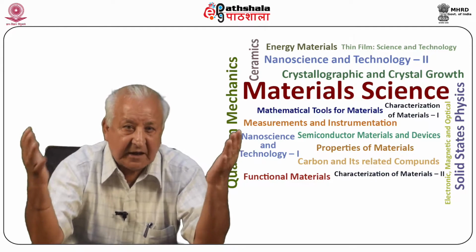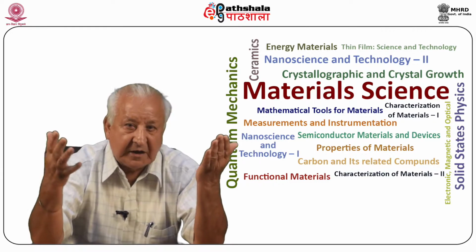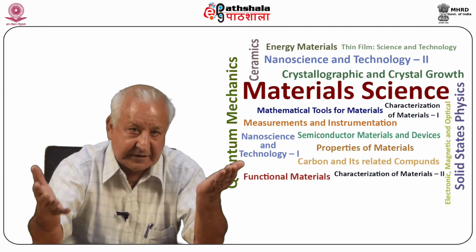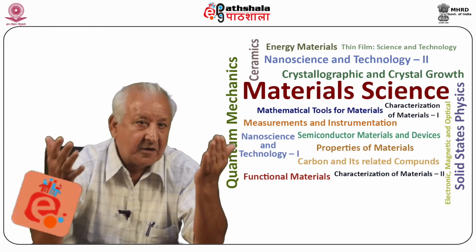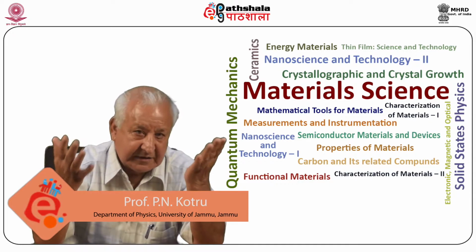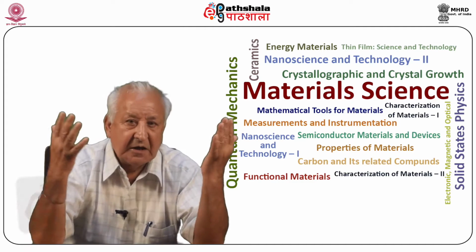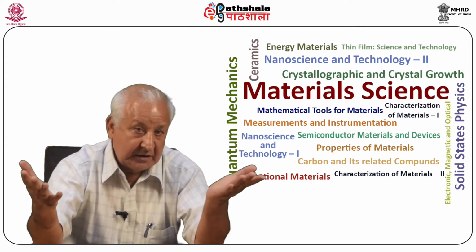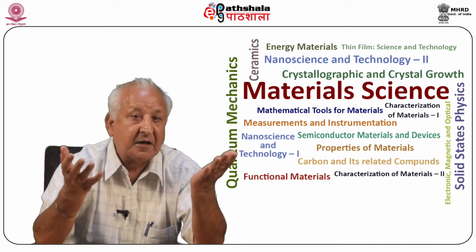Zone melting as a technique of crystal growth is explained. Floating zone technique of crystal growth is also described. Apparatus for zone melting or refining of materials involving volatile components is also described. Other processes of growth from the molten phase, including flame fusion, modified Verneuil growth, arc fusion and skull melting, are explained.